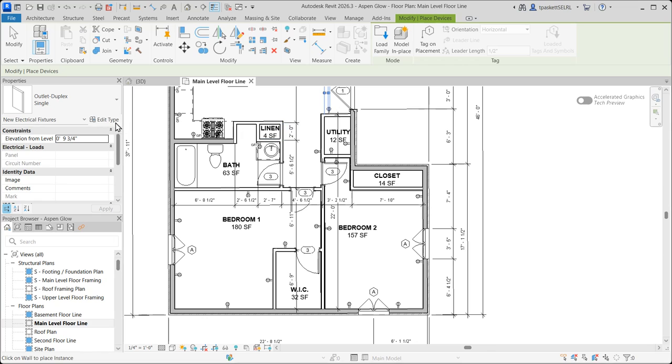If you then go outside, and you should put outside outlets, let's go find that one. We need a waterproof outlet. Well, I'm looking in here. I do not have a waterproof outlet. So what am I going to do? I'm going to use this GFI, the same one we've been using. So I'm going to duplicate it. It's going to say single 2. I'm going to put on here WP for waterproof, and I'm going to hit OK.